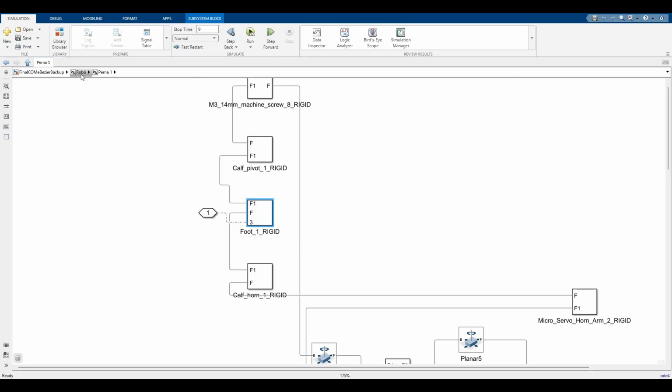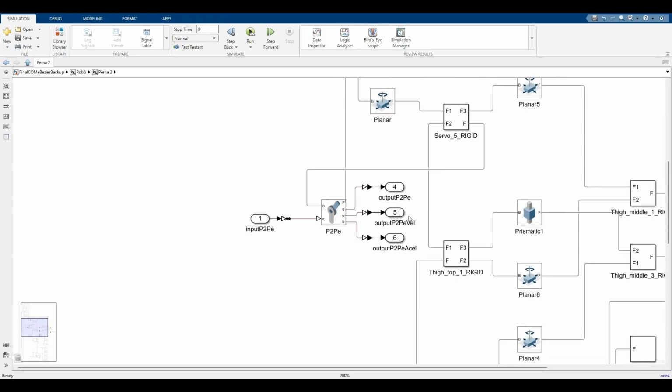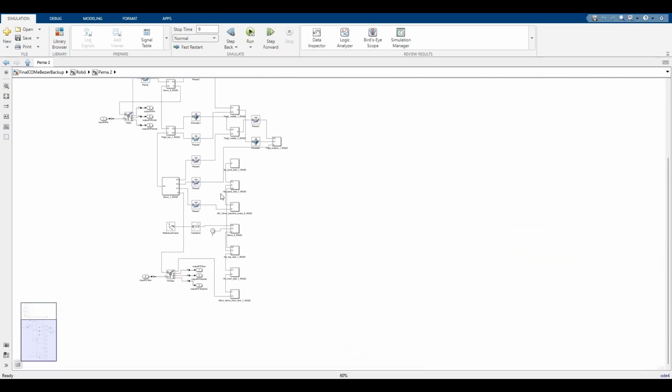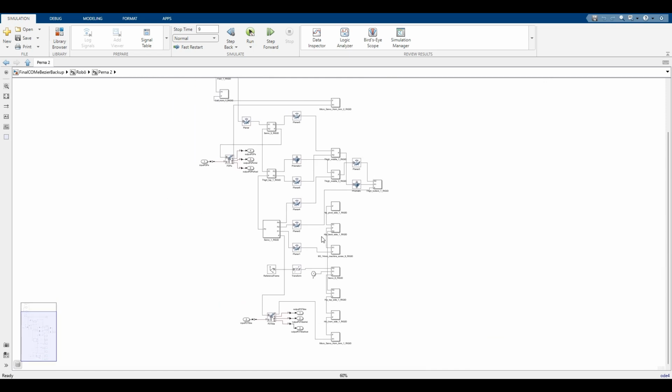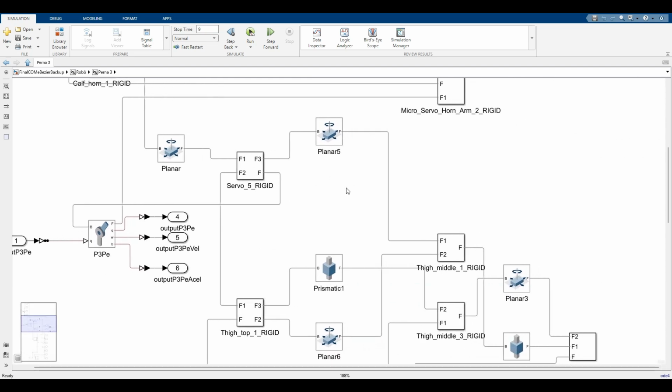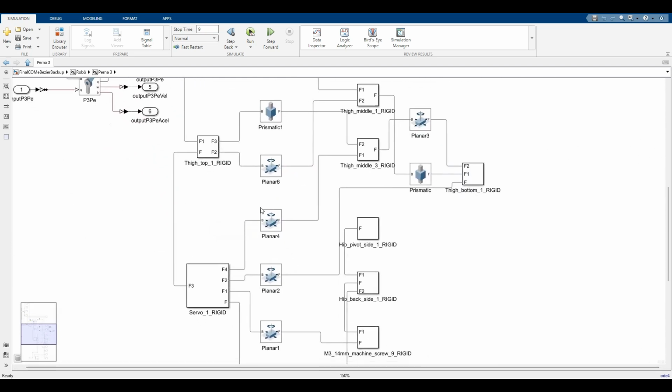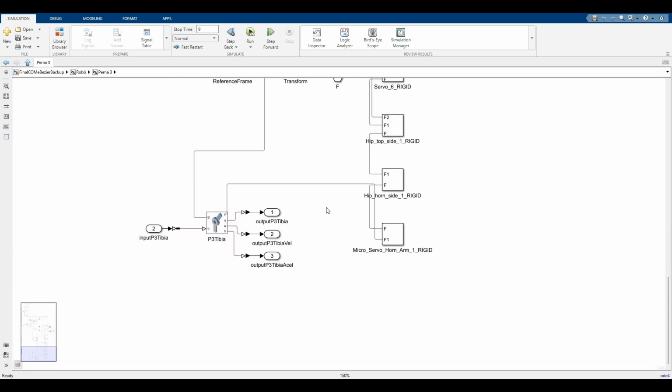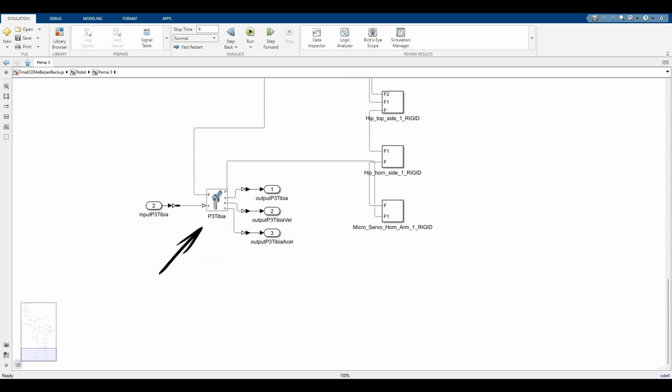This simulation environment enables us to evaluate the forces and torques acting on the robot, such as inertia, friction, gravity, and others, which are crucial for accurate physical implementation. Each revolute joint provides 3 essential output signals for robot analysis: position, velocity, and acceleration. Additional joints are employed to ensure that the multiple elements of this complex mechanical chain perform cohesive and stable movements.